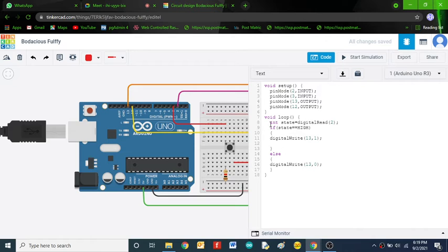Okay, so this is the function, so just copy and paste one more time, so then we'll easily modify the numbers. Most people will use this kind of structure, but don't use this kind of structure. Just read the status of the pins at the start of your code, so that it is very easy to read. So I will make a simple modification here: just remove the digitalRead statement here and place it at the top.